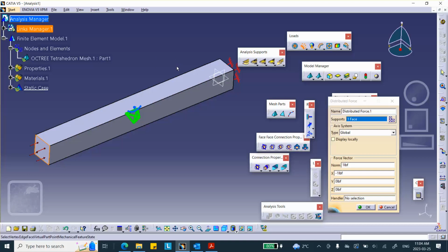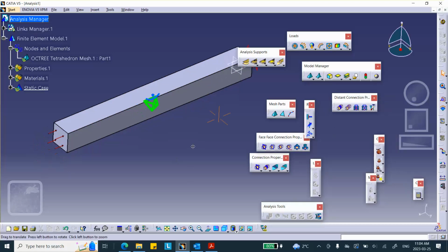That means there will be no buckling with a positive. The load will be in compression, therefore those factors are going to be negative. But here I already put it as negative, -1, therefore the buckling factors, or the scale multiplier, is going to be positive. Okay, so that's pretty much it.